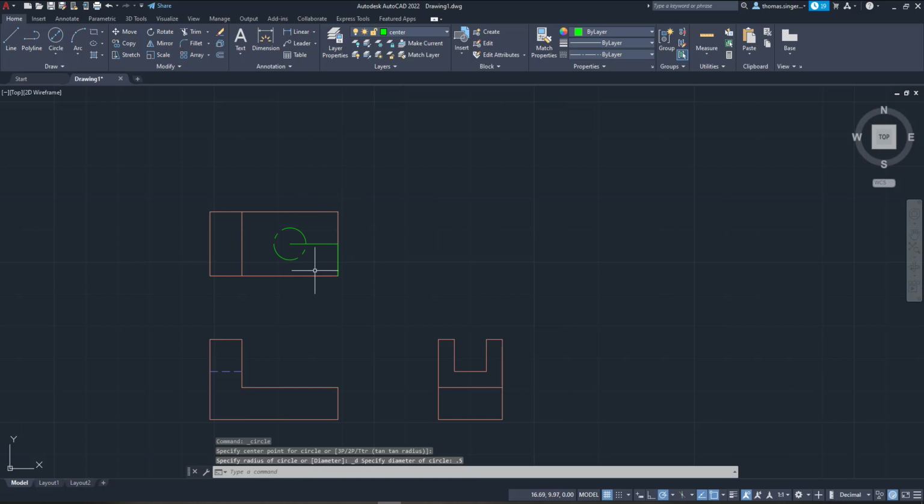And we drew it on the wrong layer. That should have been solid. So now we have to pick the object, choose the drop down layer, and then pick the layer, and then hit the escape key to get out of the blue dots. So let me do that again. Let me undo. Pick the object with a left mouse click, choose the correct layer that I need to put it on, and then hit the escape key to get rid of the blue dots.